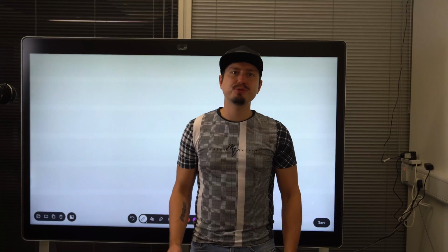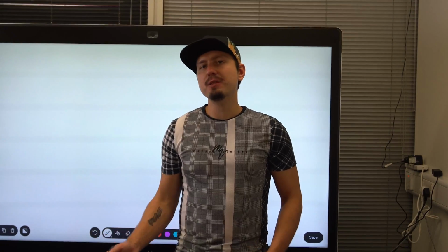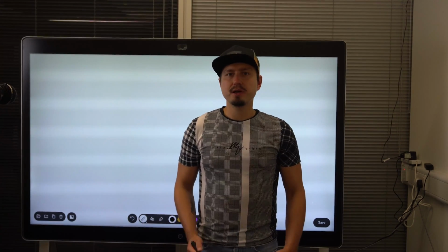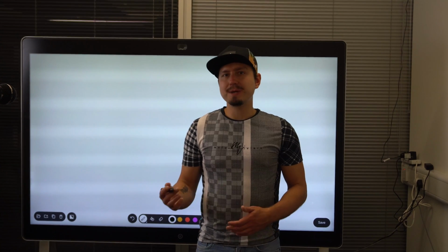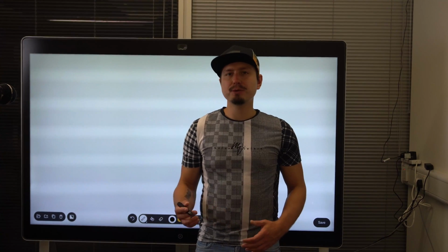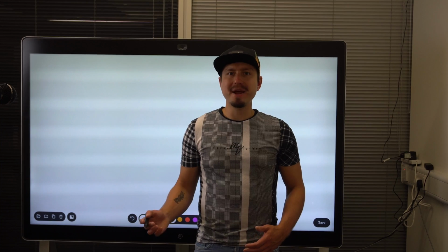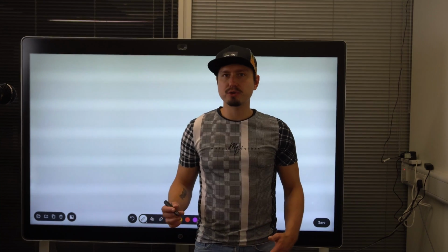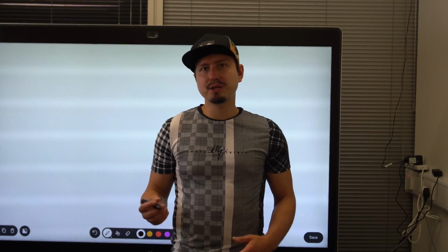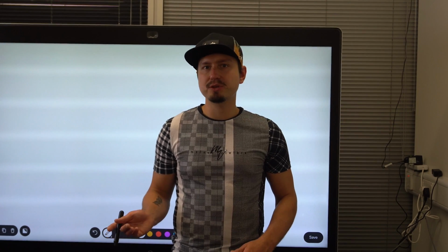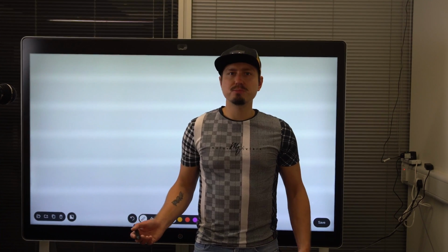Once we finish drawing schematics, this is now time to do the PCB layout, right? Wrong. Actually, there is one more thing we need to consider before that, and that is shielding. And we need to make sure that we understand exactly at what points the connections are made to the shield on our circuit board. So, for example, those could be pillars that connect the chassis to the printed circuit board, or this could be connectors, such as a USB connector.